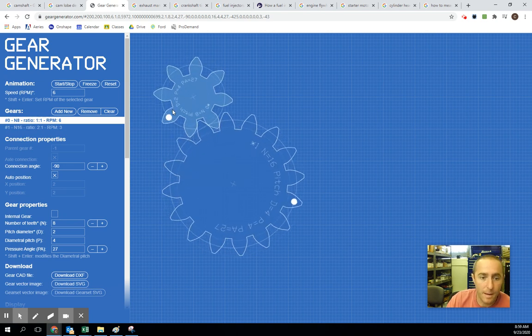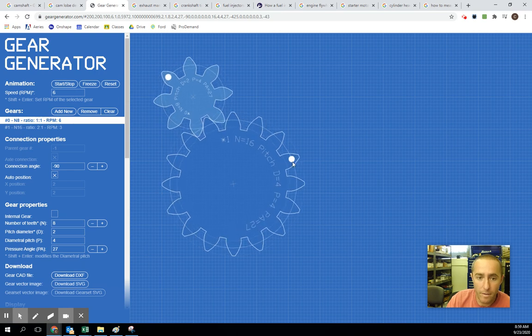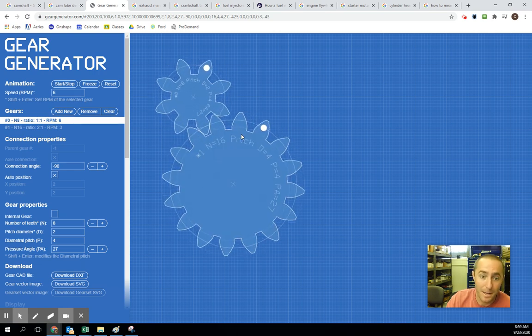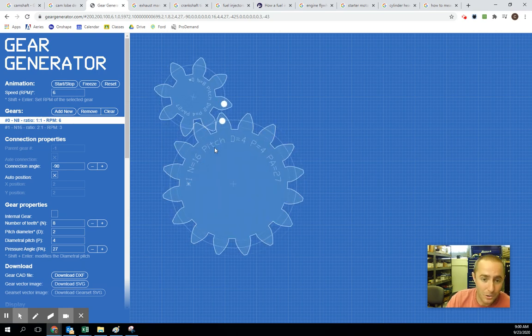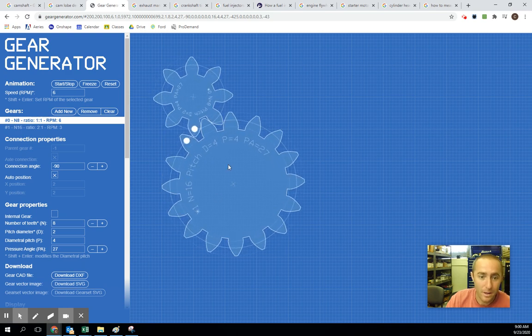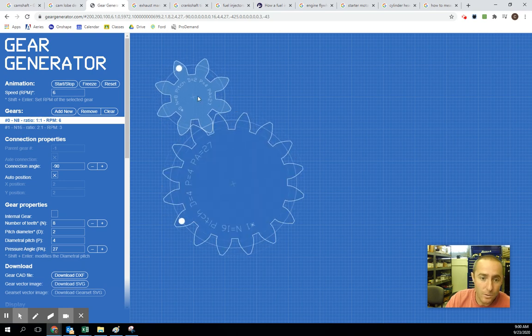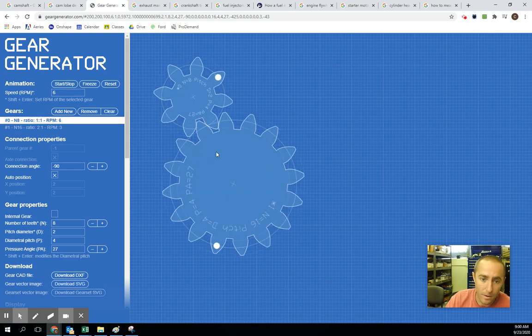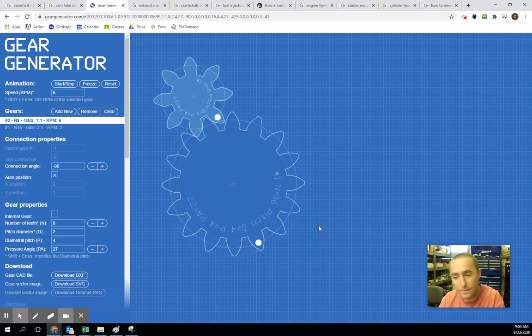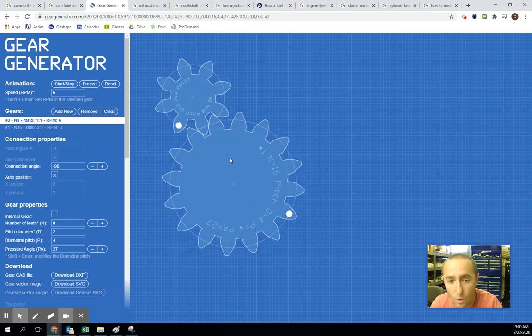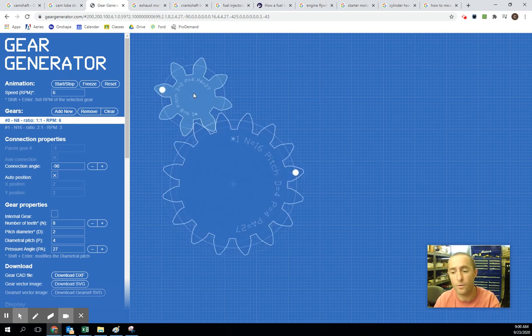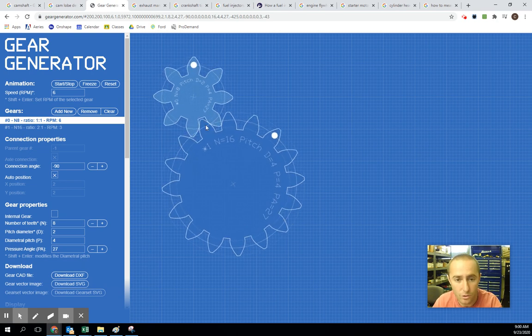As this goes around, I'm doing my intake stroke. This is opening a valve. It's closing a valve. Now it's not doing anything. We're having a compression stroke. We're having our power stroke. Now it's opening another valve for our exhaust stroke. So these two timed together is very important. But for all intents and purposes, you have to understand that it's always a 2-to-1 ratio for every vehicle. The ratio between these two will be 2-to-1.